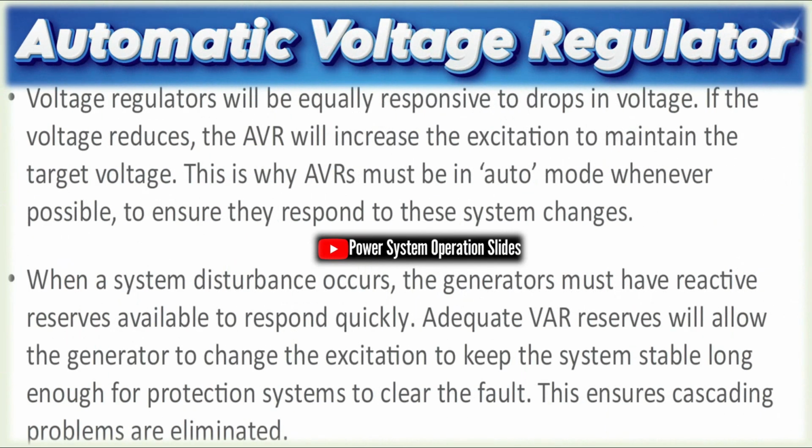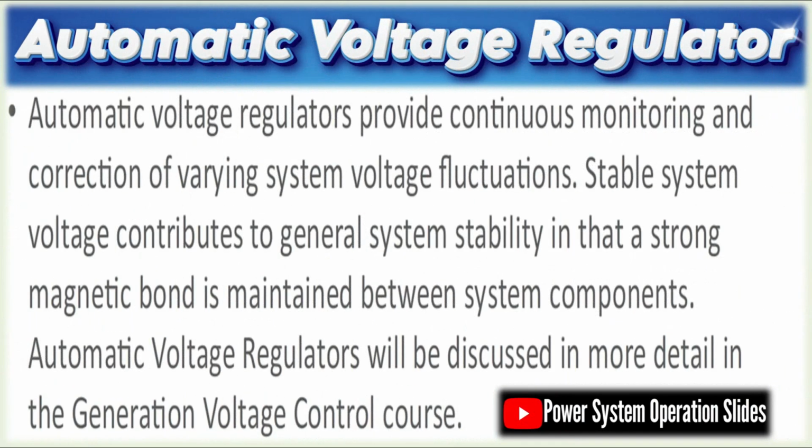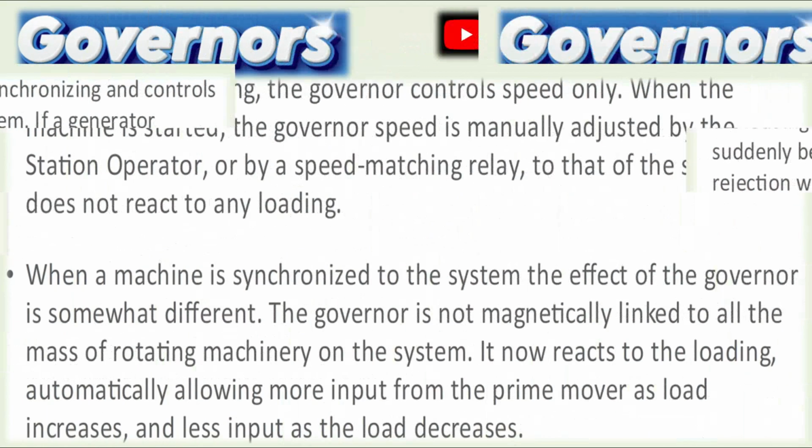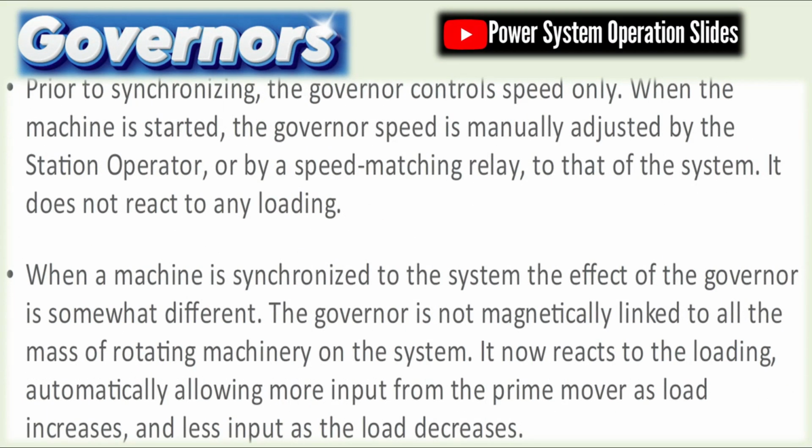Fossil fuel power generation: coal power generation involves complex processes, fuel handling, combustion, flue gas treatment, ash handling, and waste heat recovery. Supercritical and ultra-supercritical boilers operate at high pressure and temperature for better efficiency. Natural gas plants are favored for their flexibility and reduced emissions. In open-cycle gas turbines, the thermal efficiency is lower, around 35%, but in combined cycle operations, it can exceed 60%.